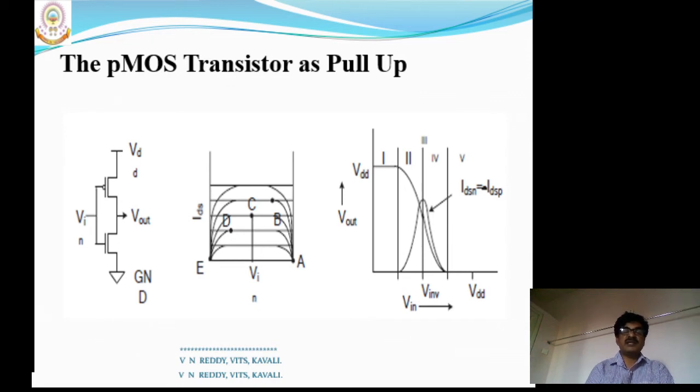That is one advantage of this CMOS inverter. And another thing is, for either logical low or logical high output, only one transistor is on. Therefore, there is no direct current flow from VDD to ground. Therefore, no static power dissipation.